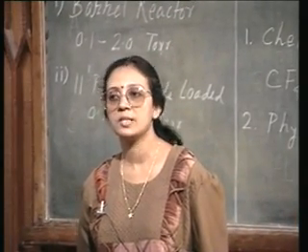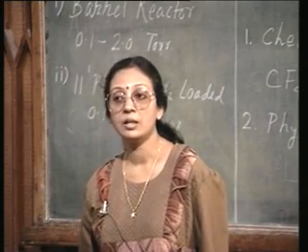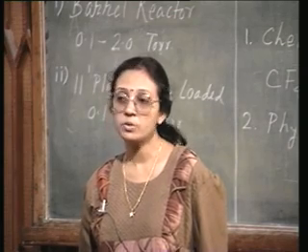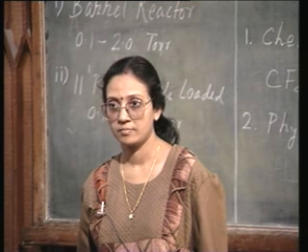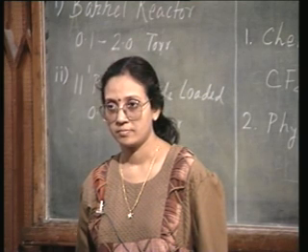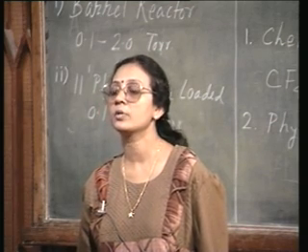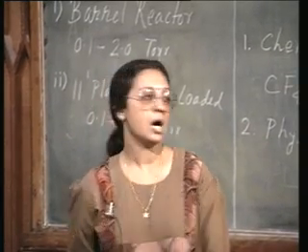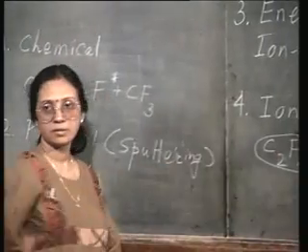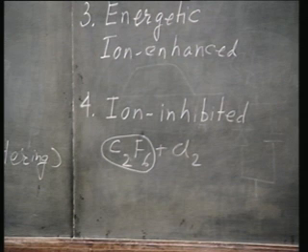So, you have good selectivity, but relatively poor anisotropy, unless of course you use special additives as inhibitors. Normally the reaction is going to be chemical, and therefore the etching profile is going to be isotropic. Anisotropy will be poor unless you add inhibitor forming gases like C2F6 so as to improve its anisotropy.